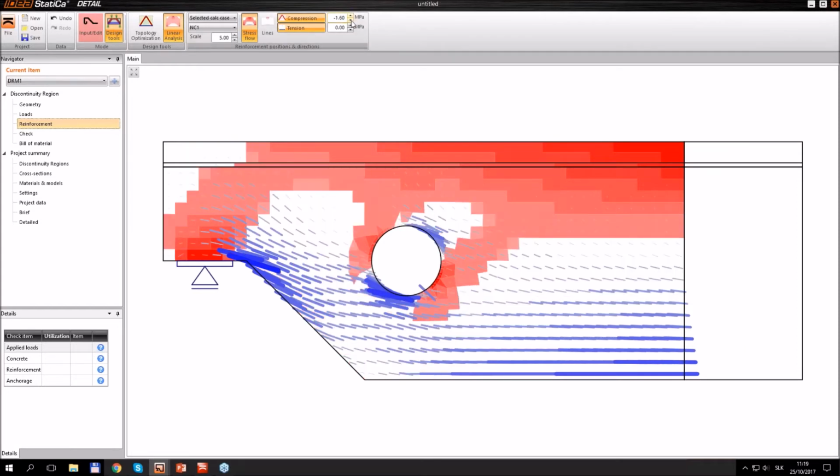So you can see the areas with values higher than a given value, and you can see which parts are under compression, which elements give us the most tensile areas, and you see which ones to reinforce, right? So you can see some beam behavior here, right? So bending, so compression up top and the tension on the bottom fibers.